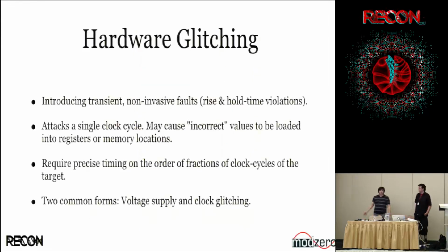So another one that I'm going to talk about, but Olivier will also talk about it more tomorrow. So make sure to come to Olivier's talk tomorrow. It's basically hardware glitching. So hardware glitching means we somehow introduce some transient faults to the execution of the system. We play around, for example, with the voltage or the clock. Those are the 2 main types of glitching. There are crazier ones like laser glitching, which we might get to see tomorrow.